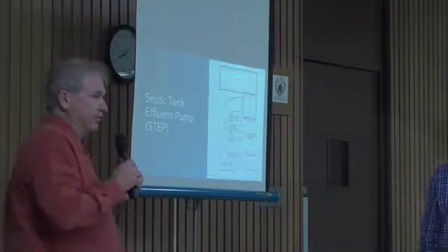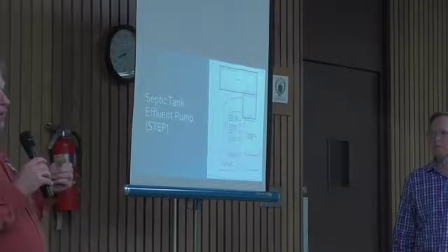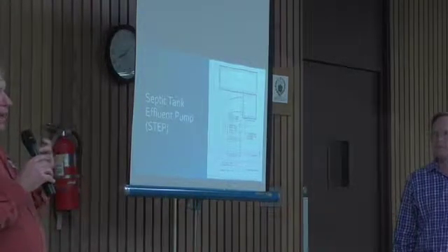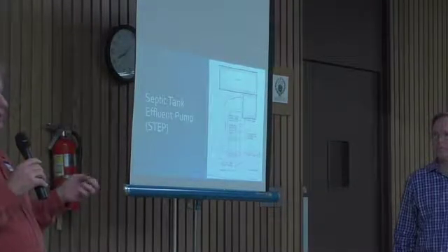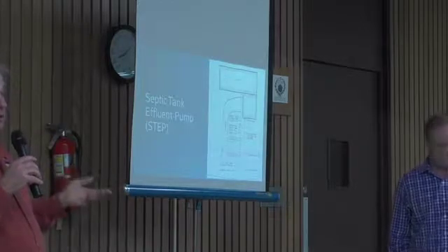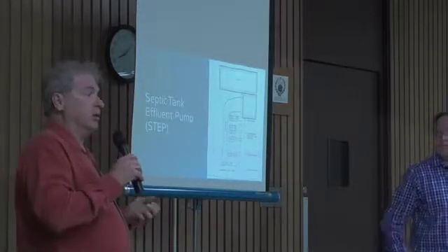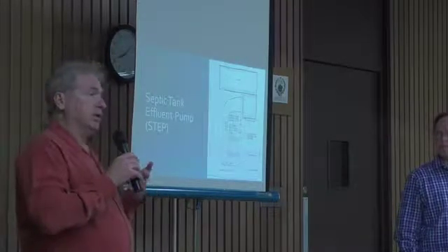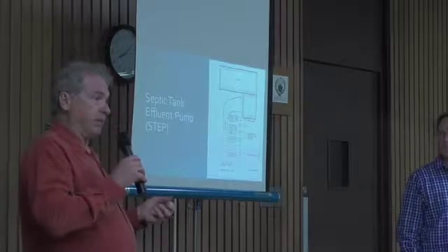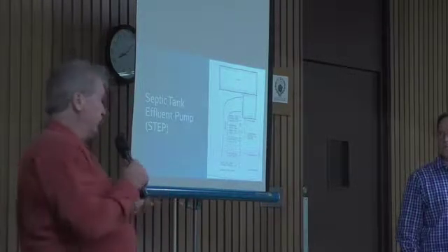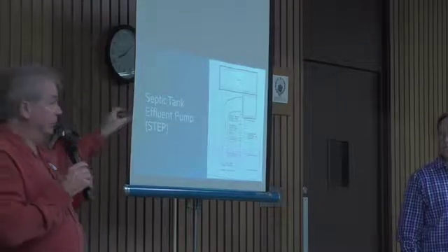And we looked at that system mainly because we were hoping that the state would allow us to have a subsurface disposal area for septic tank effluent and not have to have a real treatment system. But because of their current regulations and our water quality objectives, they want the nitrogen removed from the wastewater, and they want the organic matter to be removed from the wastewater before any type of disposal. So the one advantage of that system then kind of disappears.